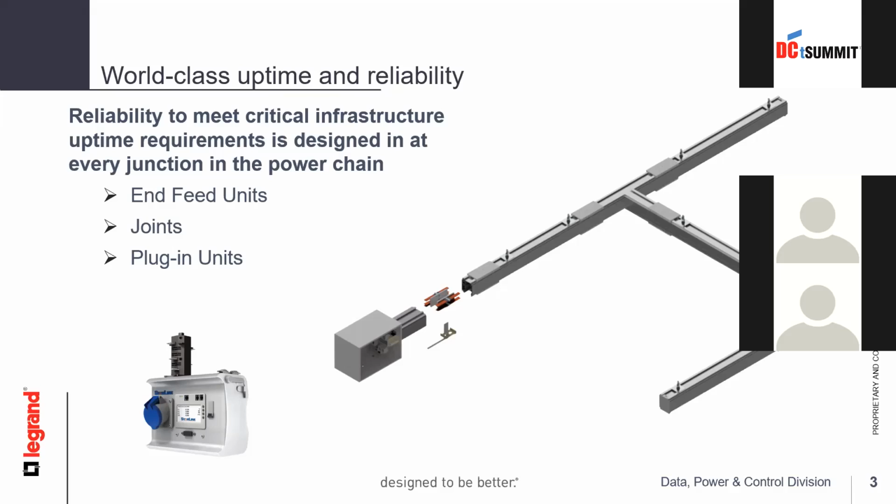And the busbar runs along the aisle. The bottom of the busbar is continuously open, so you can tap off power wherever you want using the plug-in unit or the tap-off unit. And then you can connect that to the rack PDU. So that's typically the architecture.